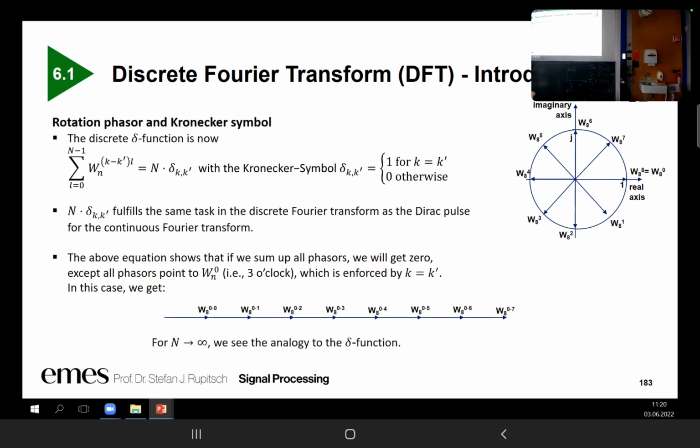If we have a sinusoidal signal, again I mentioned 50 Hz. Let us assume our sinusoidal signal has 50 Hz. Then our discrete Fourier transform will provide a frequency spectrum with a component at 50 Hz. Why will we not obtain a frequency component at 60 Hz or 40 Hz? Do we have an idea?